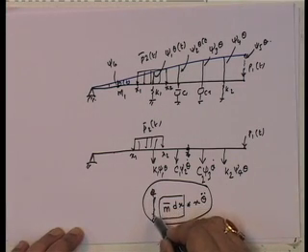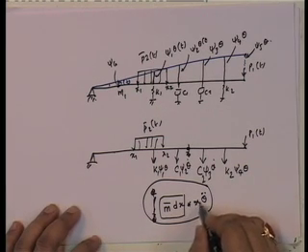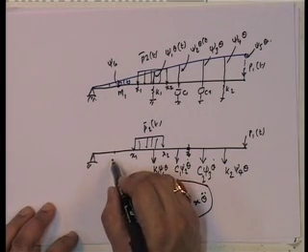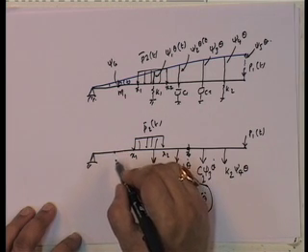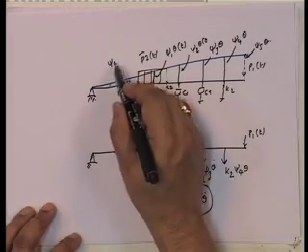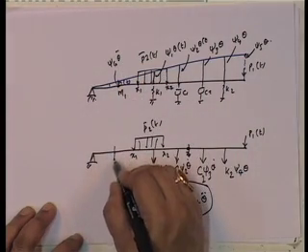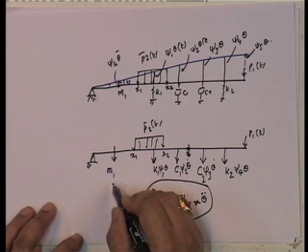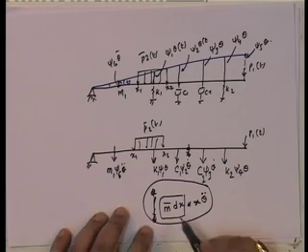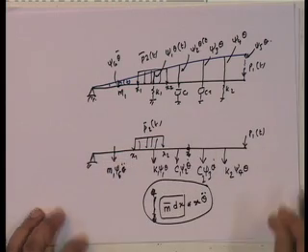However, this is not to be integrated, this is to get the total inertia force, but understand the inertia force by itself does not give anything. On top of that, we have a mass m 1 here. So, m 1 is being subjected to what acceleration? It is going to be subjected to acceleration xi 6 into theta double dot. So, this is going to give rise to a load m 1 xi 6 theta double dot, and these are the inertial forces that happen here.